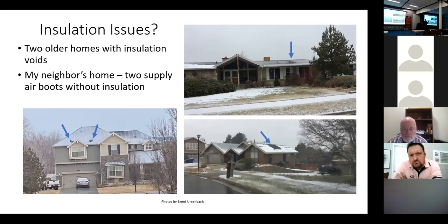And I'm being picky, aren't I? When I say every piece of metal in the attic that's exposed needs to be insulated to a minimum R8. But that's what the code says. And what does building science say? That's what we want to do. And in fact, R8 is a ridiculously low amount of insulation. It really should be R24 or something like that. So yeah, you're not out of line saying all the metal insulated.